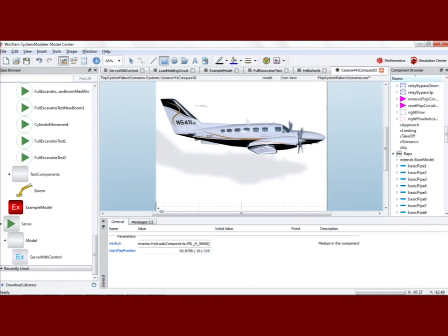Do you have a script interface to System Modeler? Can you write scripts? Yeah, well, you can write scripts through Mathematica. So you can use Mathematica for scripting it. Is there a specific thing you would like to do? No? So if you want to have things that are run during the simulation but run externally for some reason, you can include C code, Fortran code as external code and use that as input for your model. But you can then also use the Mathematica environment if you want to script simulations, for instance, or programmatically create models. So you can kind of do whatever you like from the Mathematica environment with both the models and the simulations.